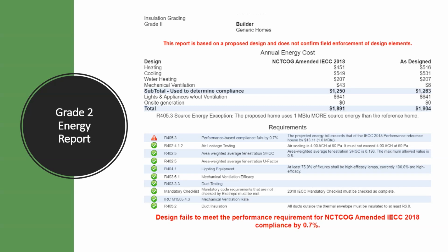If you see big red letters, of course, everyone knows that's not good. And it says on here, based on these elements, it's not in code field enforcement, and it does not pass the energy model. So this should be red tagged. It should be reconfirmed by the energy modeler: if I do grade 2 here, can I still pass energy code? If they come back and say no, it now fails the model, the red tag needs to be corrected. If they say grade 2 does pass, then you can record it as grade 2 and move on, and say that you're still in compliance with the permit documentation to meet the levels of acceptance for whatever pathway and whatever code version is being used.